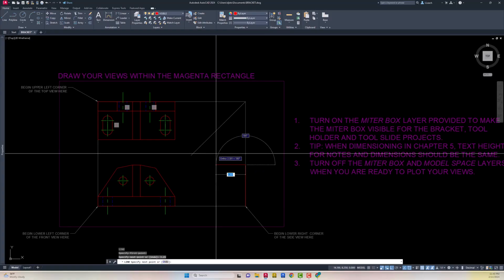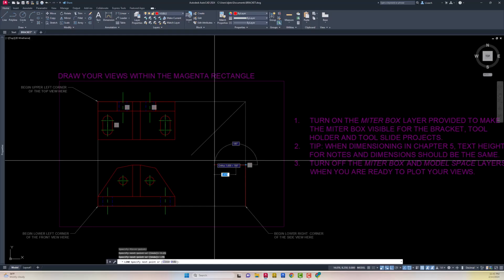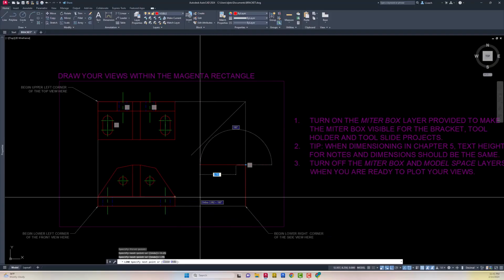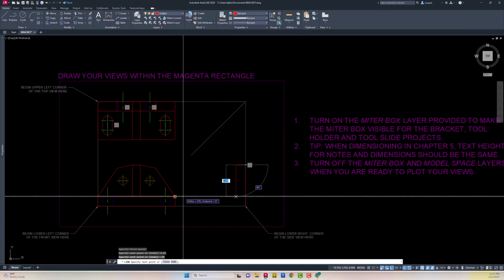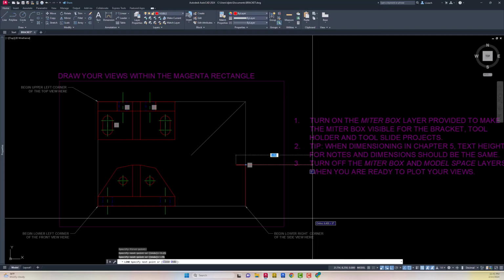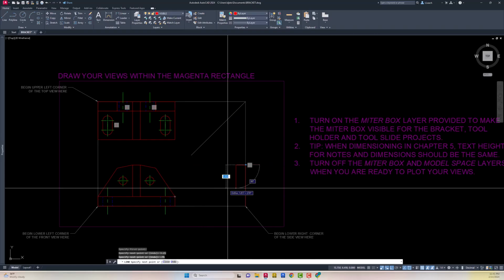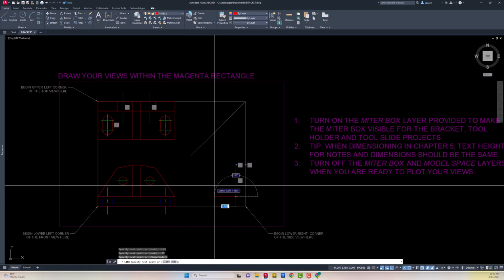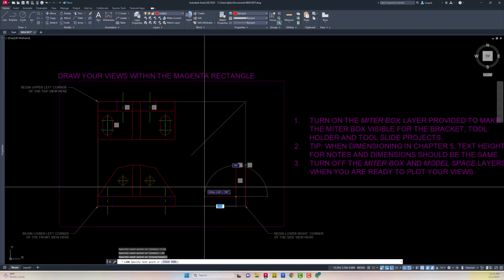And it's going to go over to the left by 0.75. It's actually going to go down. Let me see if I can grab this corner. If I just move my mouse over to this corner, because I have my constraint, infer constraints on. If I drag it over here, but I don't click it, then when I drag it down, it'll snap to that little line and I click it here. So that's an easier way to get those lined up. And then this is going to be over by 3 minus 0.75, which I'm going to call 2.25.